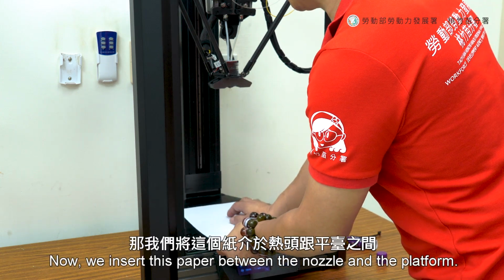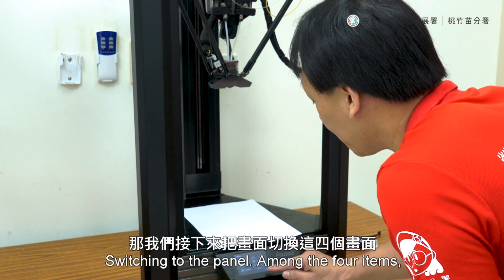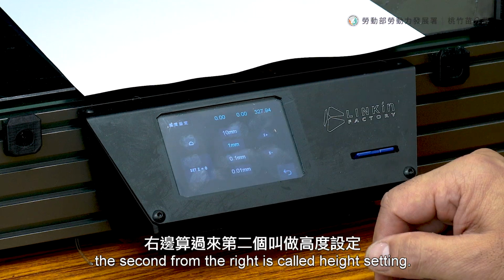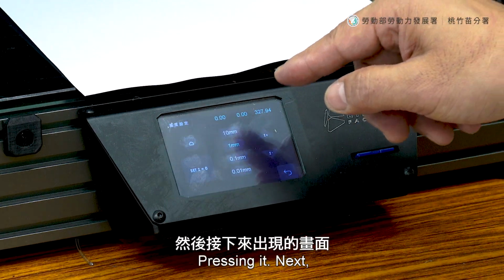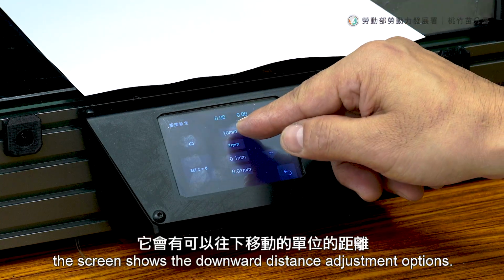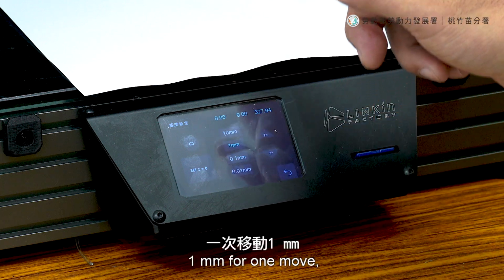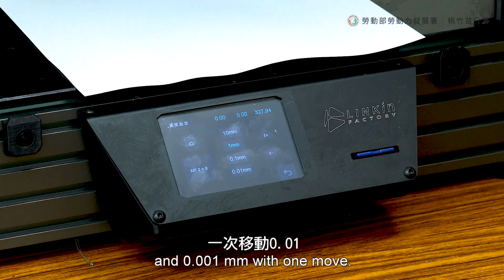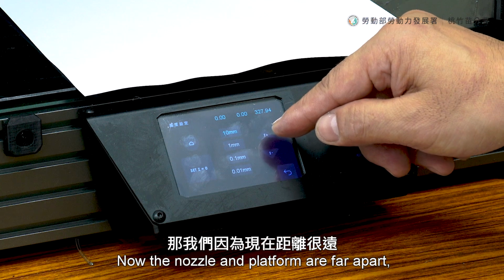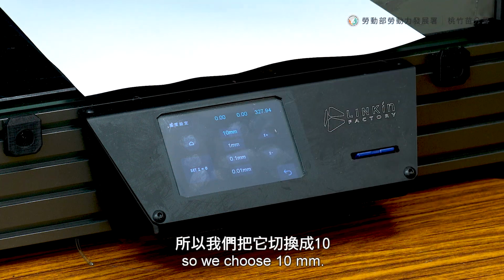Now we insert this paper between the nozzle and the platform, switching to the panel. Among the 4 items, the second from left is called height setting, pressing it. Next, the screen shows the downward distance adjustment options: 10 mm at one move, 1 mm, 0.1 mm, and 0.001 mm. Now, the nozzle and platform are far apart, so we choose 10 mm, alright.